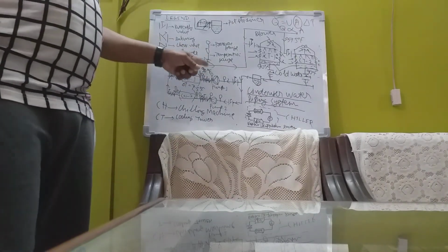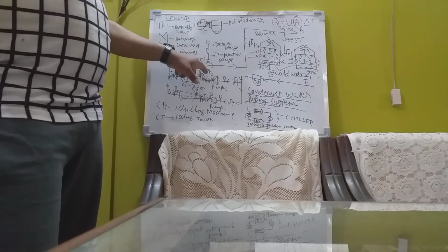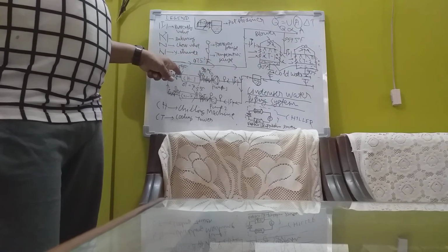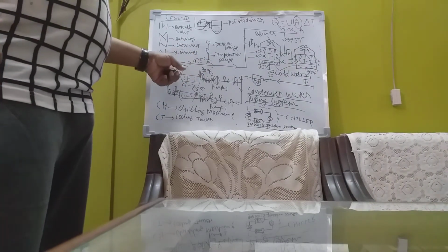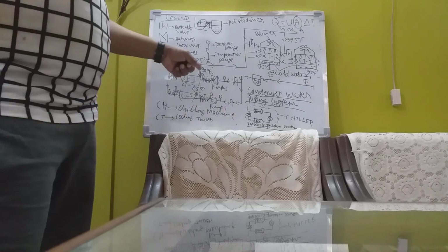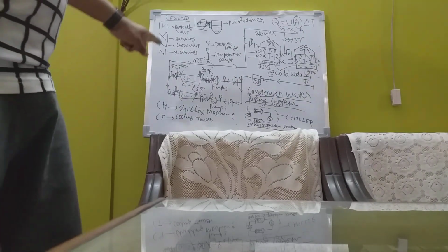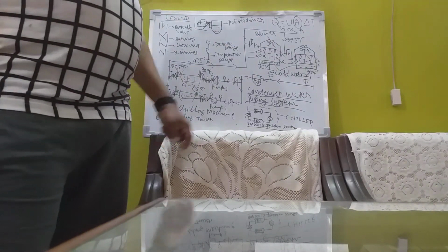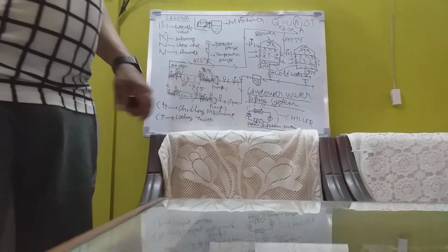I made changes. It was earlier being cooled in the case of the chilled water system from 54 degree Fahrenheit to 44 degree Fahrenheit. Now this water gets heated up because it cools the refrigerant, from 90 degree Fahrenheit to 97.5 degree Fahrenheit. So at 97.5 it again enters the cooling tower and at 90 degree Fahrenheit it comes back and the circulation happens.